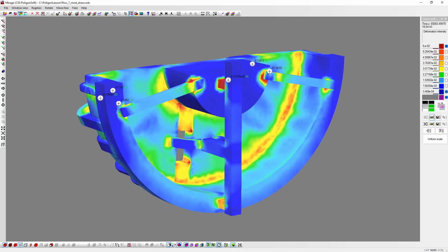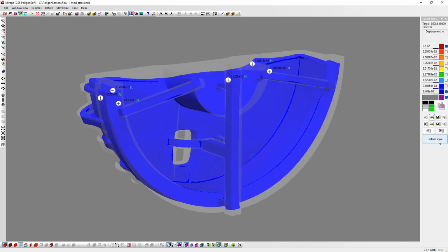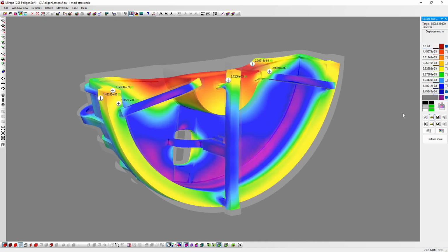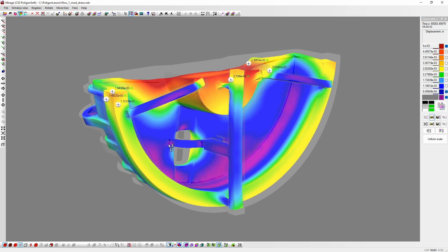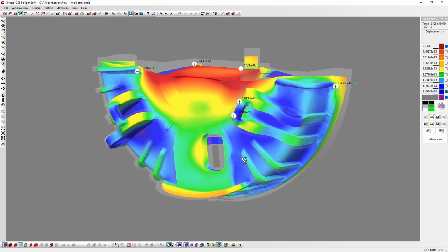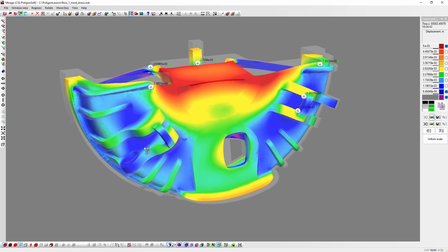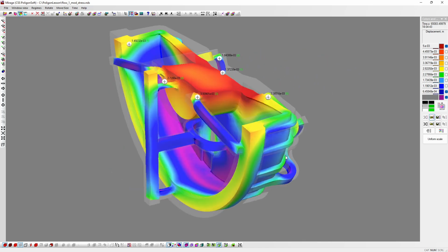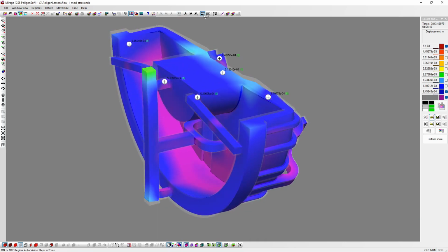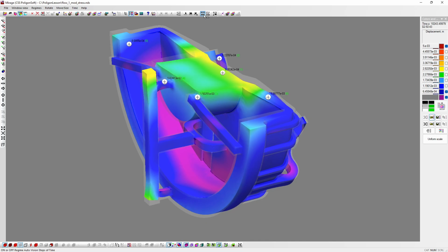Let's take a look at the displacement field. I switch to this mode and again set the scale. This scale shows the displacement of the mesh nodes from their initial position in meters. We see that the maximum displacement is in the center of the part, towards those parts of our casting that are fixed on all sides and cannot move anywhere. Here we see the modified geometry, that is, the distortion of the geometry. To better see the difference between what it was in the first step and what it became in the last, we can enable playback.